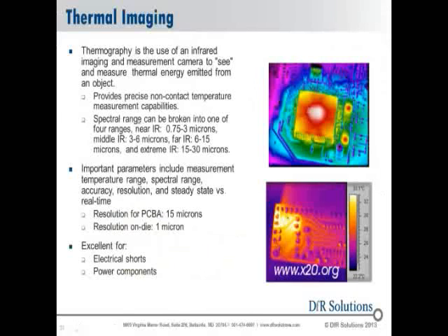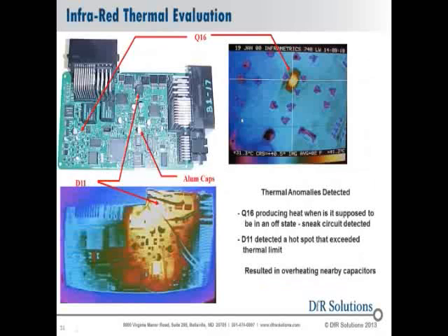Another type of imaging technique is infrared imaging, where you can look at your device as it's operating to see the heat picture of what's going on and to look and see if you have any hot spots in the device that are excessive or causing problems. Some other ways we have also looked at things, we said, oh, the device is so close to being off, but here we've got a sneak circuit. This device is still getting a little bit of current through it and it's heating up.